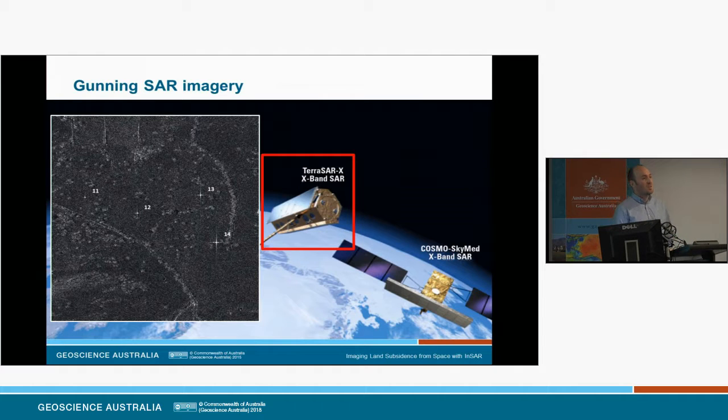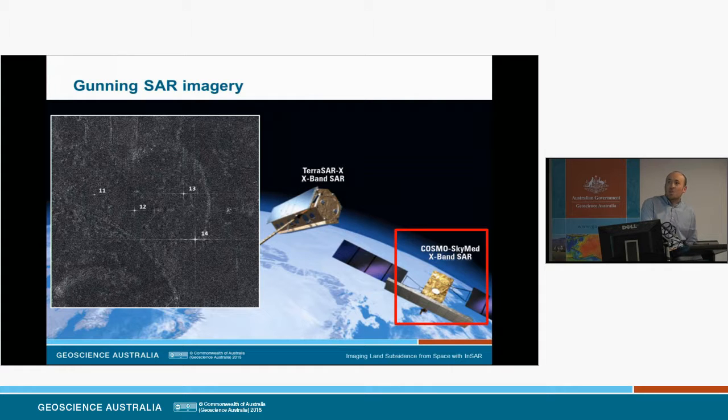And this is a function of the limited bandwidth of the SAR that is used, and the processing that's used to focus this image was a Fourier transform and a match filter. But it gives this characteristic impulse response function for each corner reflector. If we compare that now to the Cosmos SkyMed image, you can see a similar thing.